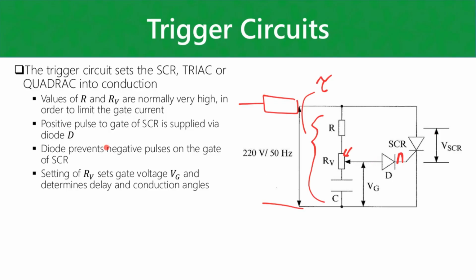All right. And I'm pretty sure you guys know how an SCR works as well. So maybe just quickly explain here. For an SCR, basically if it's forward biased and you have a gate pulse applied, your SCR will continue to conduct as long as it stays forward biased, but the gate pulse can be removed. You don't need a gate pulse or a signal applied to your gate consistently. But let's say for some reason your SCR gets reversed biased, that also cancels the current through it, and it will stop conducting. Or if you interrupt the current flowing through it, then it will also stop conducting until the next gate pulse.